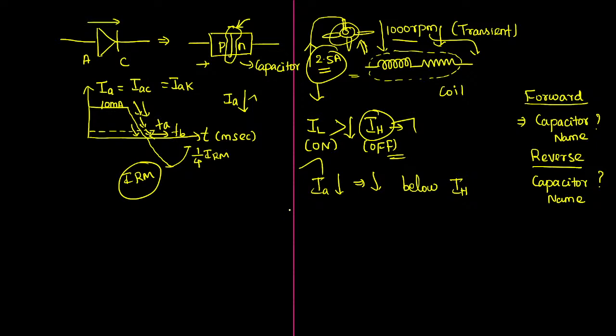Now they are coming to the next point. Sir, how to turn off? They asked whether there is any possibility to turn off this same device using voltage. Let us come to that point also. When we are talking about voltage, what will happen to the SCR? Voltage in the sense, we have to reverse the polarity, right? Yes, sir. Basically we have to reverse the polarity. How do we reverse? Let us see.